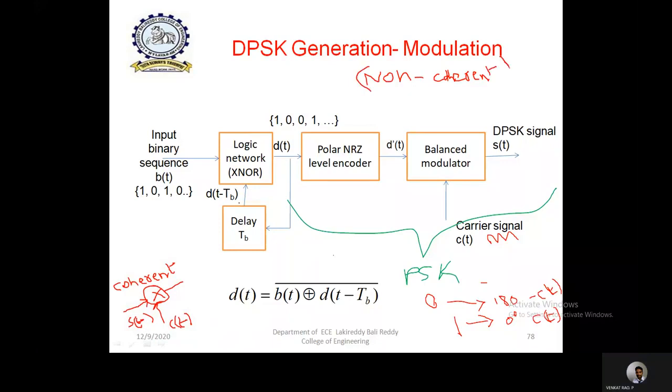The process of the non-coherent way of demodulating the PSK signals is sometimes called DPSK. That means DPSK can also be considered a non-coherent version of PSK. So to eliminate the drawback of maintaining the same coherent carrier, we can go for DPSK.